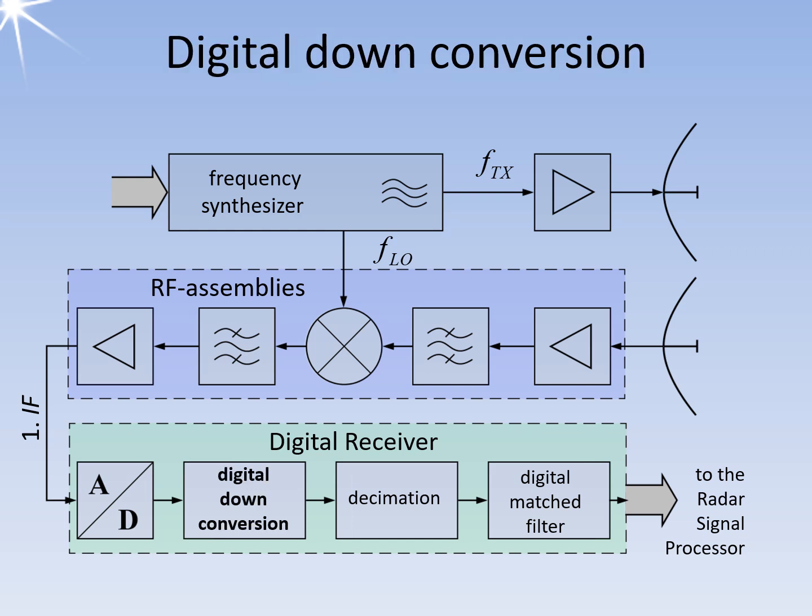The digital down conversion does the same as the analog model. Each individual voltage value sampled by the analog-to-digital converter is multiplied by a virtual local oscillator frequency that matches the sampling time exactly, and the result is stored in memory. This local oscillator frequency no longer has to be generated in real form. It is sufficient for the processor to know this frequency and to calculate each of its voltage values at the appropriate sampling rate of the analog-to-digital converter.